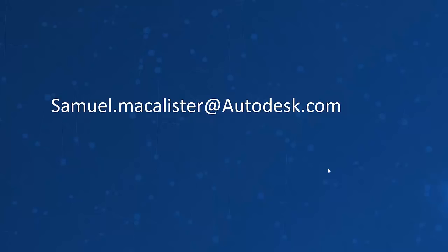Next question from Tim Jenner. Revit Collaboration or C4R for 2018.2. Yeah, so again, 2018.2 is C4R with BIM 360 team. 2018.3 allows you to use the design collaboration module.